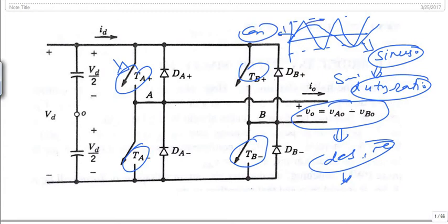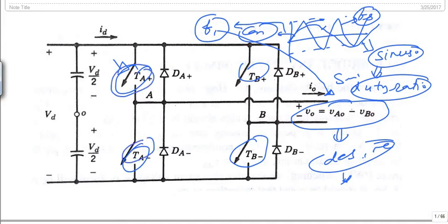The control signal frequency is generally taken as the frequency we require for the fundamental component of the output voltage, and the carrier frequency fs is actually responsible for the switching of the inverter switches.